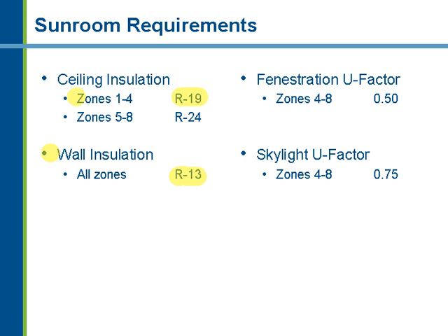And as far as the solar heat gain, the prescriptive requirements for solar heat gain are applicable regardless of where you have your sunroom or what climate zone you're in. All the hard limits and any trade-off up to a certain point for certain climate zones still have to be used, and you still have to go to that use factor table. You're not going to see that there are some footnotes and other less stringent provisions for the solar heat gain requirement.